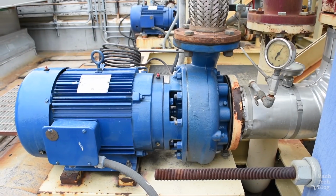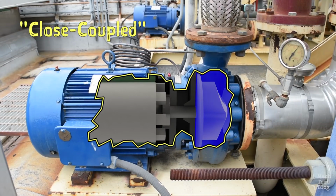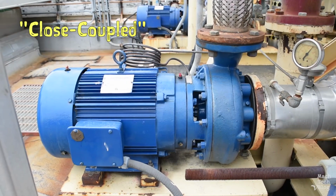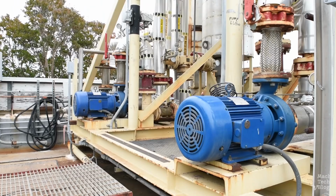A second option is the close-coupled mounting method, in which the pump and its driver share a common shaft, with the impeller mounted overhung on one side of the driver shaft. In this case, there is no need for a coupling or any of the extra labor required to perform sensitive alignment procedures. However, since both the pump components and the driver components are supported on the same shaft just by the bearings in the driver, this mounting method is really only appropriate for small and medium-sized end suction pumps.